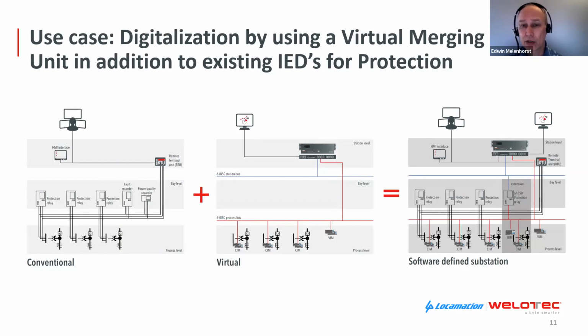Even extending the substation with additional IEC 61850 based IEDs will be less time consuming. The infrastructure is already present, working in parallel with the existing conventional relays. The big difference with the initial substation is that the network operators now have reliable and accurate process information, which will enable them to utilize the grid more effectively. Next slide, please.